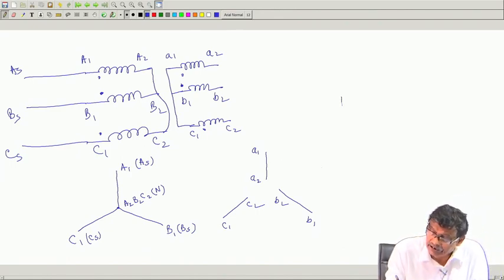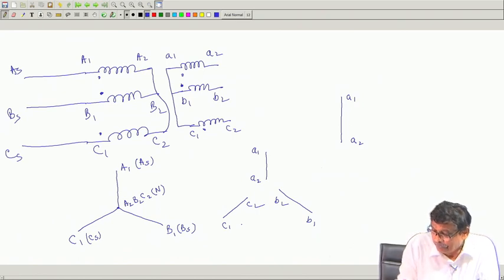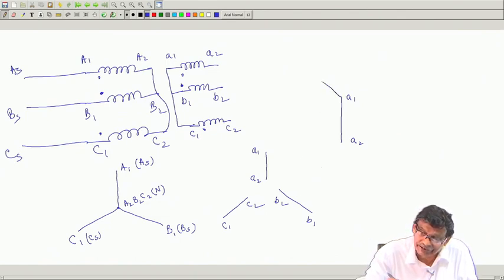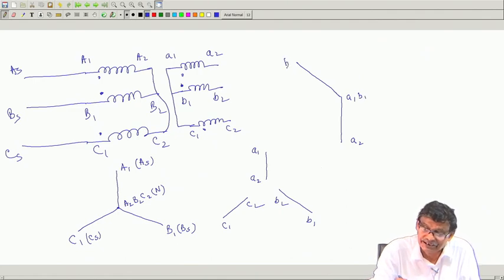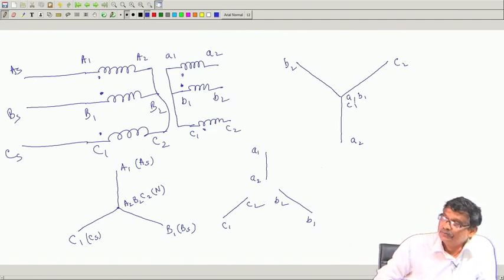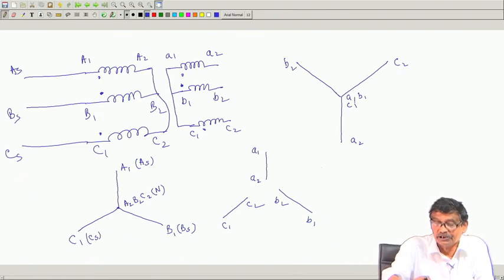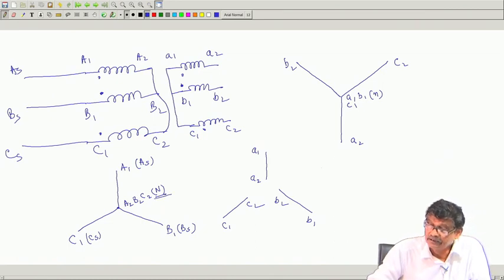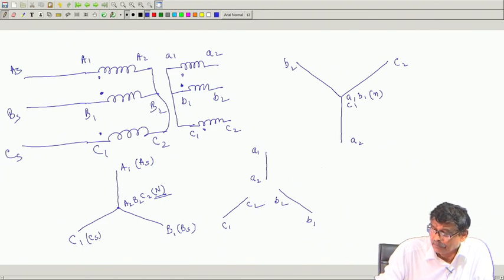So, the way you connect this is, suppose A1 A2. Now, I have joined B1 with A1. Therefore, I will move this phasor parallel and put it here, B1 B2, getting the point. Similarly, C1 C2 I will put parallel and put it here, C2 C1. Then it is also a correct balanced 3 phase output voltage you will get across A2 B2 C2. But this time this is the secondary neutral, and A2 B2 C2 is the primary neutral. Also see the supply phase sequence is ABC, everything is fine, and there is no mix up of these terminals.